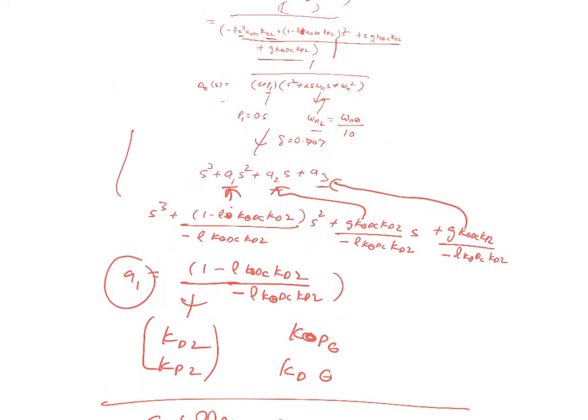So you multiply this whole thing. P1 is what you chose, let's say it's 0.5, and then S squared plus 2 zeta omega n. So 2 into 0.707 into, let's say, 0.4, because omega n was 0.4. You compute these coefficients, multiply, and then you get the desired characteristic equation. Okay, I understand. Good.